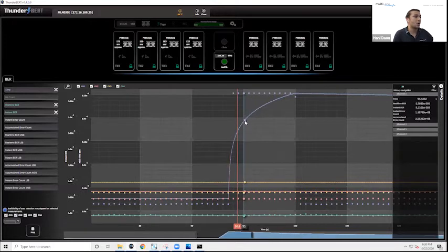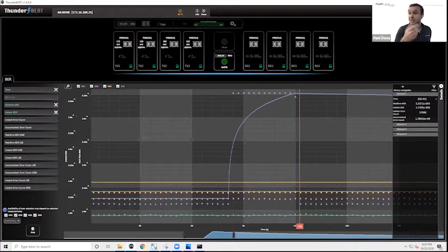So I'm going to go to different points in the history navigator, and you can see, at any point in the test, you have the visibility to get exactly what was happening at that moment. Something we have not offered in any of our software before that we're very excited to offer now. And you remember, at around 100 seconds, I turned off the error injection. So at that point, the instant BER becomes better because I'm no longer injecting those errors, but the real-time BER reflects the whole story up till that point. The 1E minus 6 plus the error injection, and then removing the error injection again.